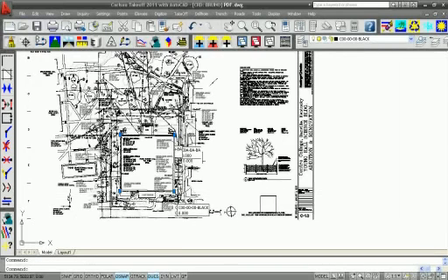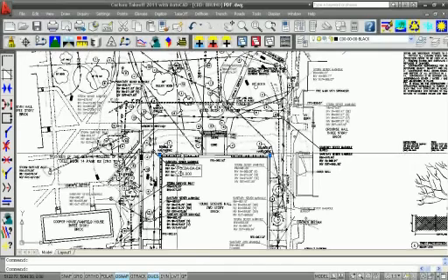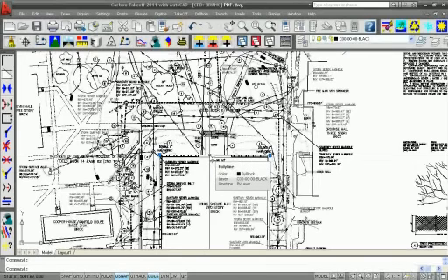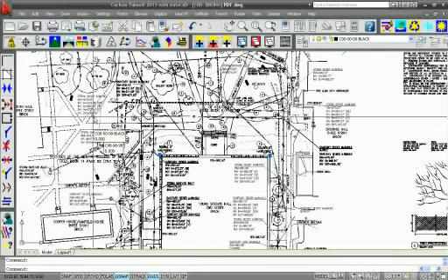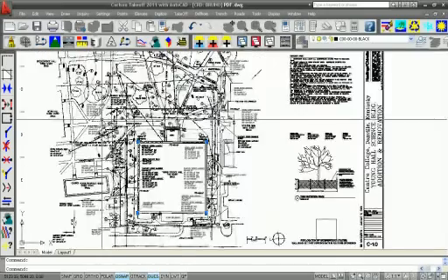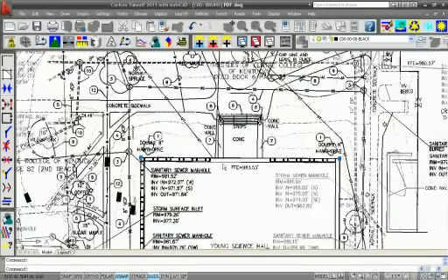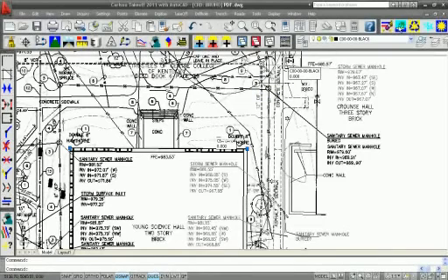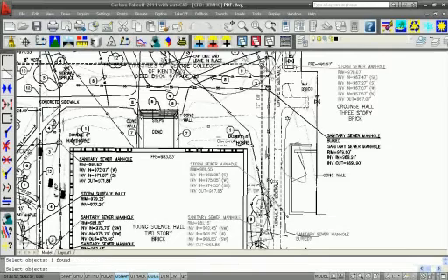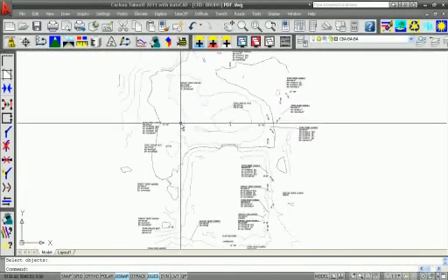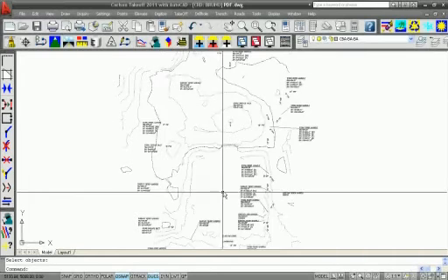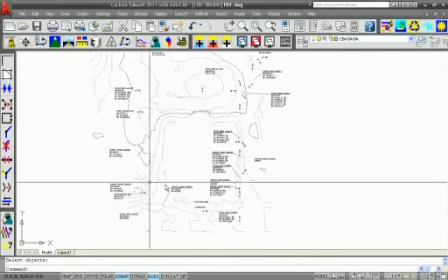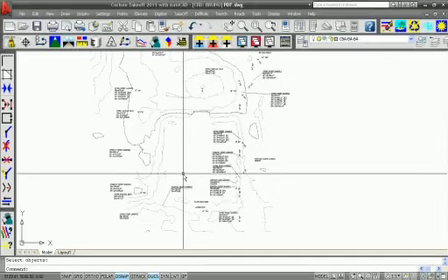And we're picking up the layer it's on? And we're giving it a layer, default layer. Okay. Yep. As you can see, I could isolate layers. Now, if I use the little palm tree, isolate, and I click on one of these layers, okay, I can see they're parsed out as contour lines because they're a different grayscale than the rest of the line work.